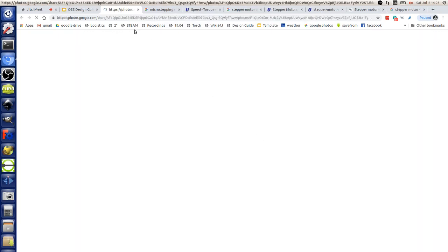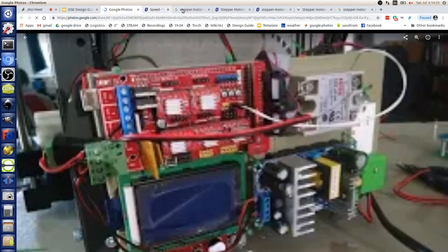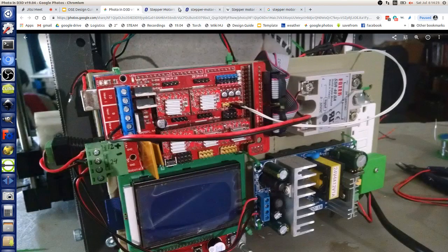In the OSE, getting to very practical aspects of this, with the OSE universal controller, we've got the RAMPS and the screen and power supply and plug and other components. The power of the universal controller is that you can plug in either your small little Pololu-style stepper drivers right into the board, or you can use bigger ones. We mentioned that you only need three signals: the enable, step, and direction signals. So from the Arduino, you're only using 3 pins underneath these stepper drivers.